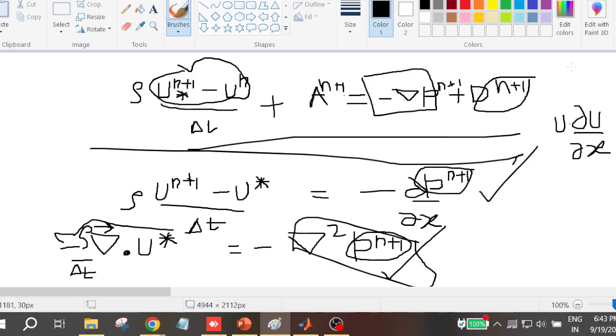We have ∂²u/∂x² term or ∂²u/∂y² term that we can easily write. It's a linear term only. Here it becomes a non-linear term. Okay, so what compromise we do is that this is usually termed as mass flux term. This mass flux we take it from nth time step only.